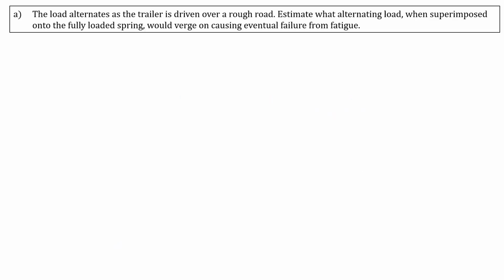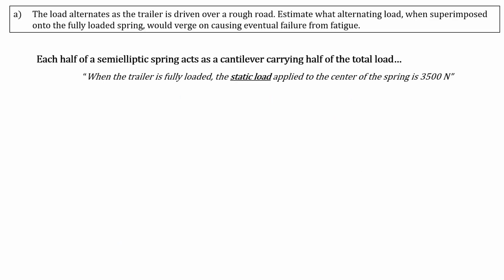So for part A, one of the strategies that we can use is that we can see that each half of a semi-elliptic spring acts as a cantilever carrying half the total load. So we can basically just split it up into the cantilever situation, apply half the load, and complete the analysis in this way.